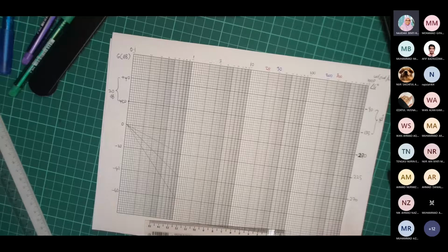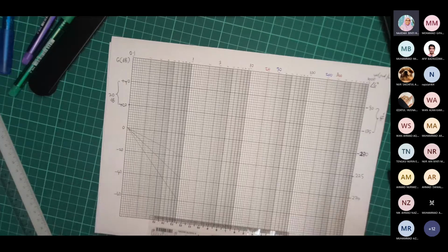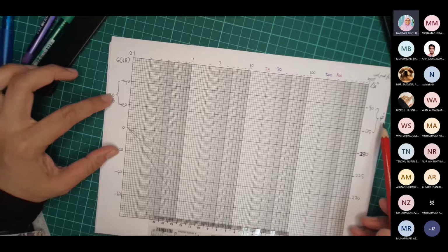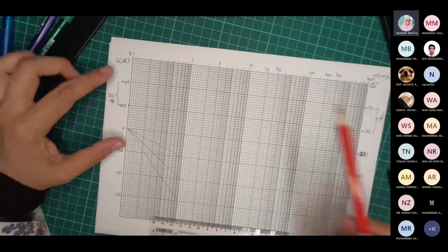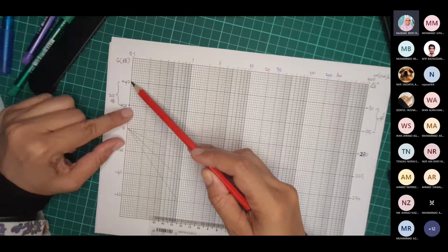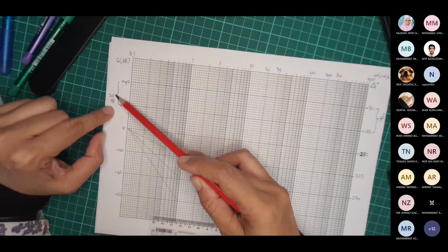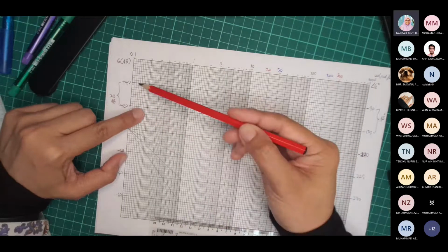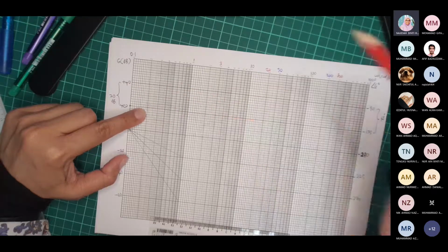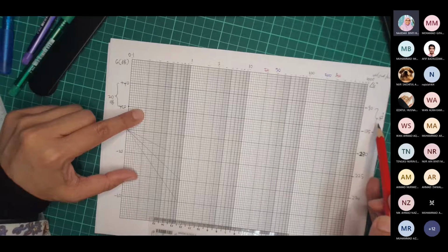How about the slope for phase plot? This is why you need to have the same scaling, 20 dB and 45 degree. Between the two bold horizontal lines, I decide the y-axis scaling for the magnitude plot is 20 dB, with the same amount of boxes between two bold horizontal lines, I decide for the phase plot is 45 degree.